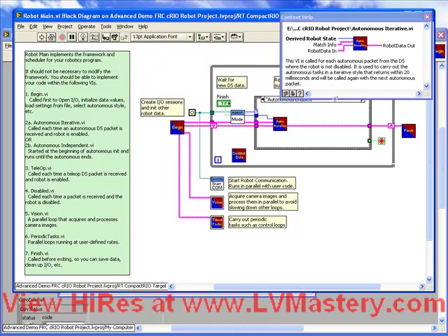From the point of view of the Robot Main.vi, the iterative mode is like a process you have to look at every 20 milliseconds. You have to look at it, make all the calculations, and spit it out again. Whereas the autonomous independent VI is like a process that you spawn. You tell it to start, you give it the data it needs, and then you forget about it until it's finished. There are advantages to both. My personal recommendation is that you use the autonomous independent VI, unless you're a very advanced LabVIEW programmer.